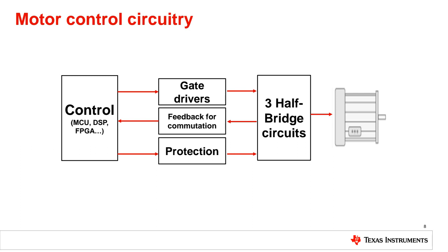Also, we have gate drivers. In your project, for example, you will use gate driver IR2110, I suppose. It's called a gate driver. Every MOSFET, every IGBT needs a gate driver because of the gate signal. Gate drivers generate a signal to the gate input of your MOSFET and IGBT. You need to use gate drivers, another module.